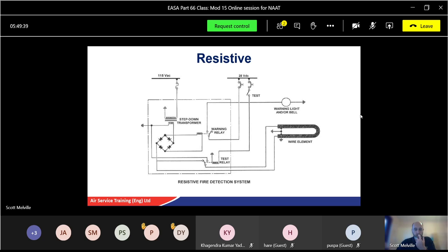When the temperature drops, the dielectric filling material will return back to its standard insulating abilities, and then it will switch the circuit off. So it's very, very similar to what we've seen on the previous one. It should be noted that the current path is always through the filling material, the dielectric, which governs the strength of the current. With this arrangement, the warning system is not compromised should a break occur in the loop. Okay, so it's not compromised that way. So again, it's a bit safer.